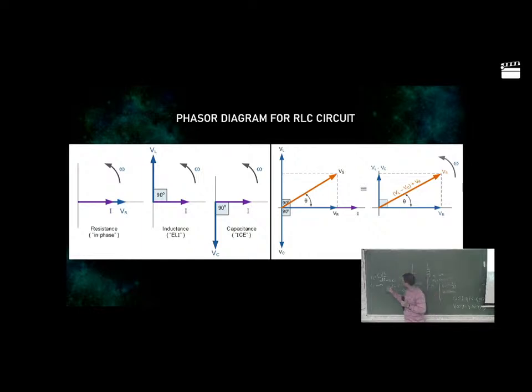In that interval, IC will tend to infinity because t tends to 0. For that infinite current, we would require an infinite amount of voltage across the capacitor, right? That's the reason the capacitor does not allow it, because we are not supplying an infinite amount of voltage across the capacitor.